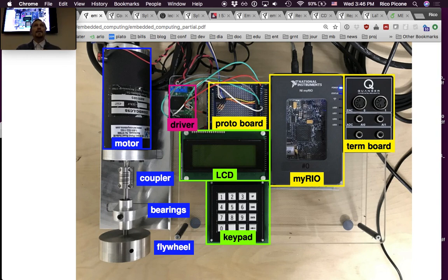An inductive load is one that has a lot of inductance to it. From our electronics backgrounds, we understand that with inductors, if we change the current through them rapidly, for instance, if current was flowing through an inductor and you flip the switch and stop the current from flowing, a very large voltage would result across it.